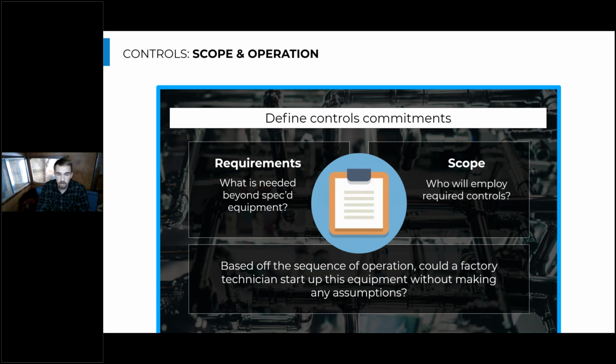So you want to make sure to collaborate with the manufacturer early on in the design and the installation detailing process to make sure that those small setting details are ironed out and that the sequence of operation can actually be satisfied by that heat pump's settings and requirements.